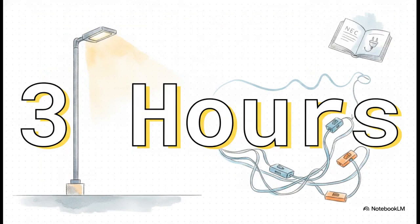Now, here's a number you just have to burn into your brain. 3 hours. If a load is expected to run at its maximum current for 3 hours or more, think of, say, a commercial parking lot lighting system that clicks on at dusk and runs all night long, the NEC officially calls that a continuous load. This one single definition drastically changes how we size our wires and breakers later on.